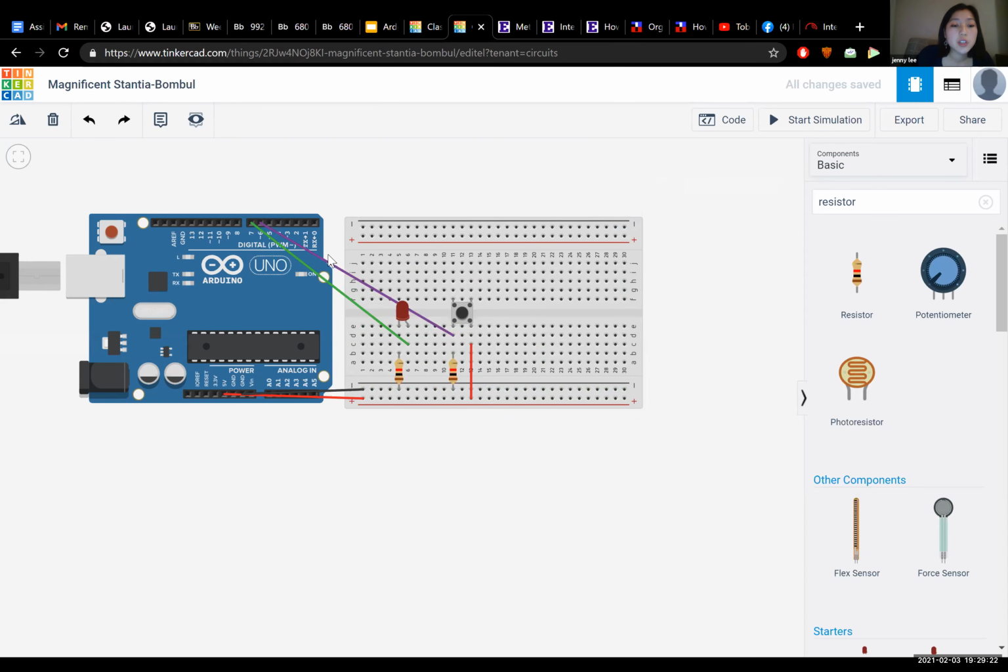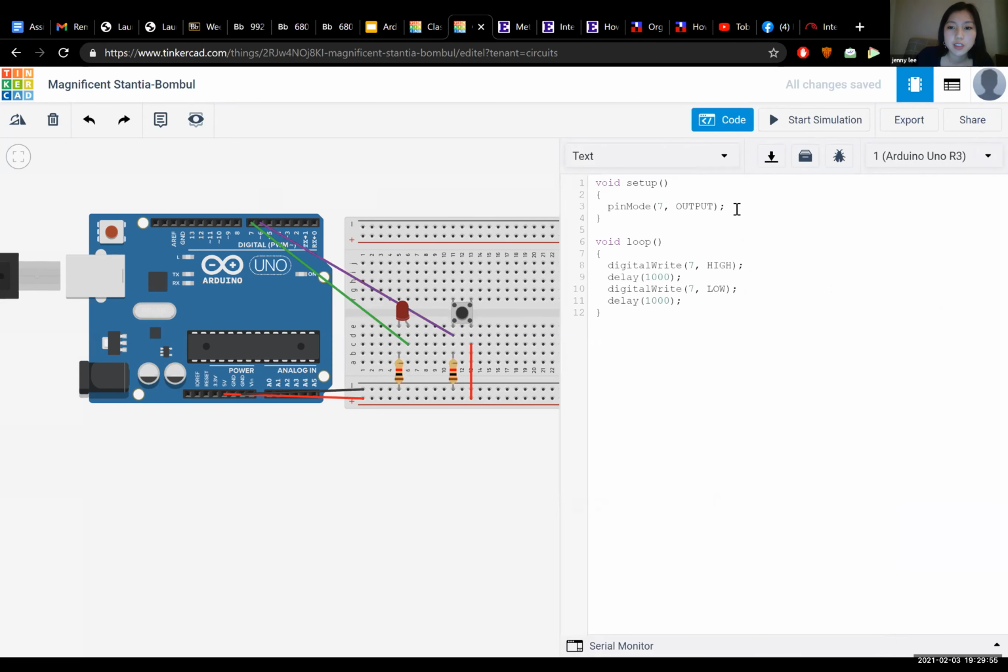And now if you declare this as an input into the Arduino code, it's going to be able to read whatever signal is on the button. So as I mentioned before, if you press the button, that's a digital 0. So the Arduino, if it sees a digital 0, it's going to understand that the button is pressed. But this is kind of backwards because even though it's a digital 0, intuitively, if you press something, you think it's going to be a 1. So the Arduino IDE kind of abstracted this a little bit. And if you check if the button value is high, that means it's pressed. That's a little bit confusing, but if I show you the code, it'll be easy again, I promise.